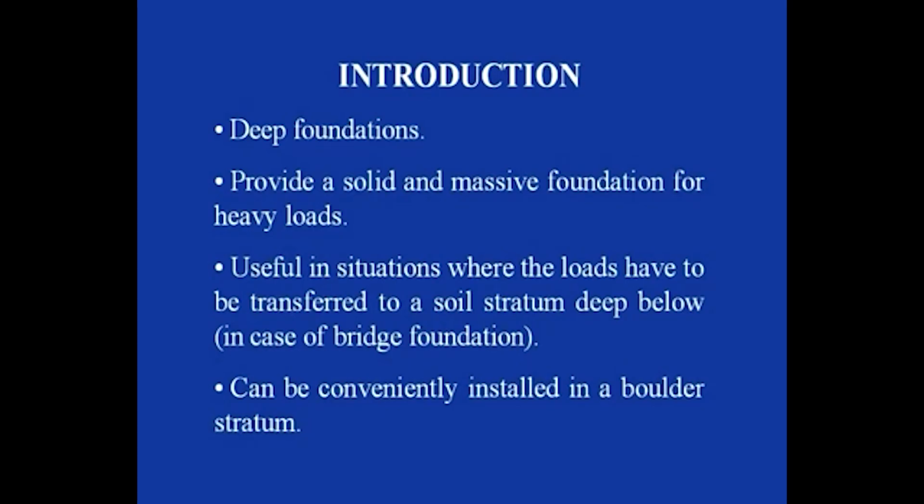It is useful in the situation where the loads have to be transferred to the soil stratum which is deep below the ground surface, for example in case of bridge foundation. This can be conveniently installed in a bouldery stratum, which is usually found in case of bridge foundation. It is very widely used in India as foundation of bridge piers as well as abutments.